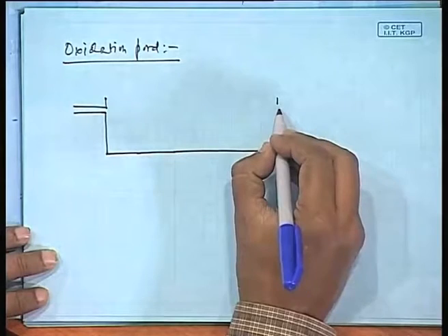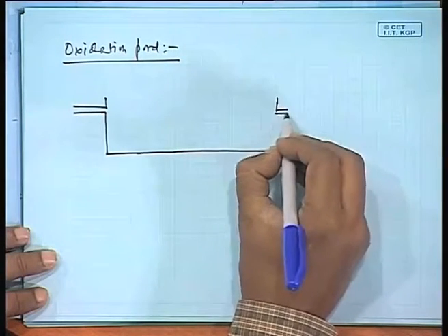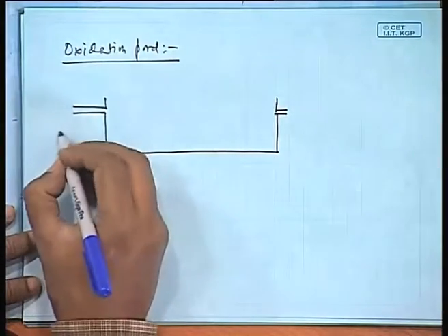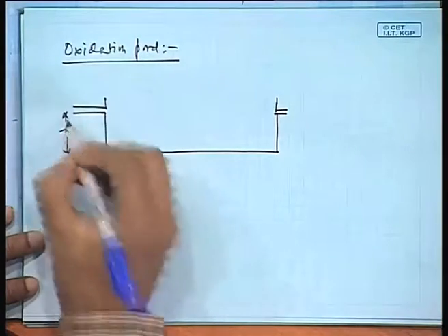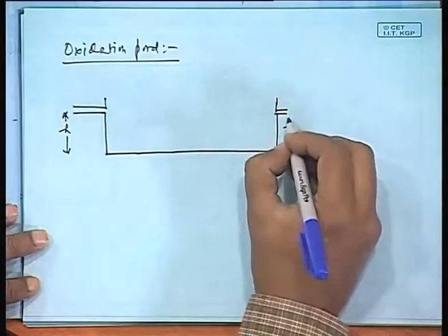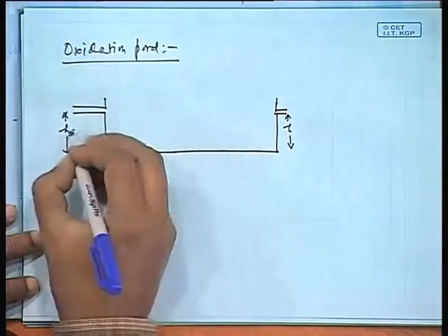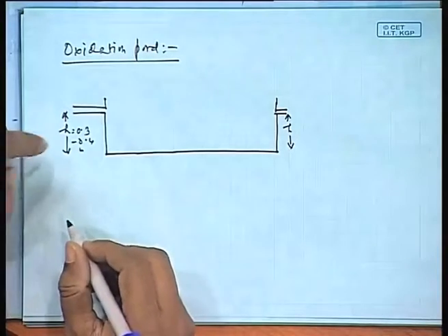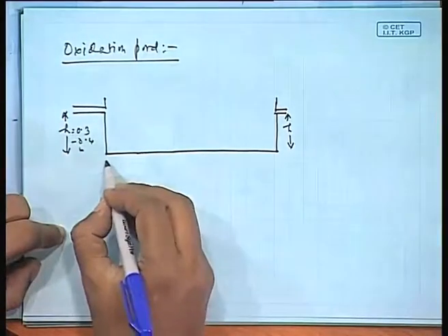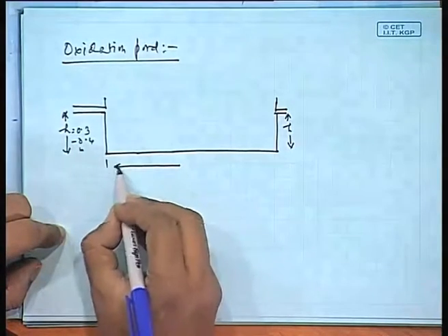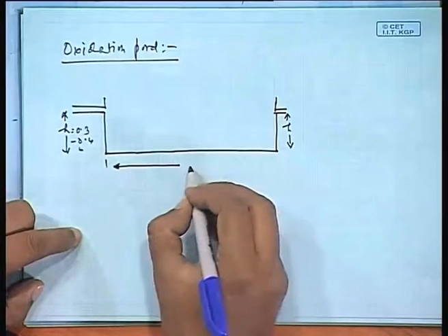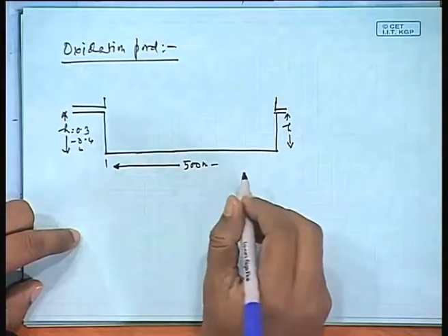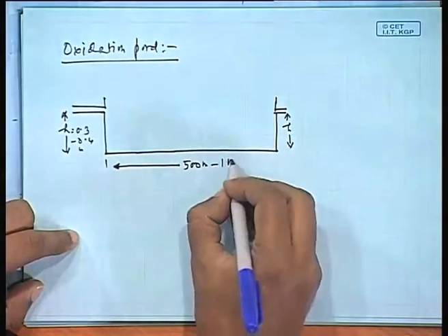The height of the effluent is mostly the same throughout, and the depth is 0.3 to 0.4 meter, or about 30 to 40 centimeters. The tank can be as wide as possible, and as long as possible, sometimes between 500 meters and up to 1 kilometer.